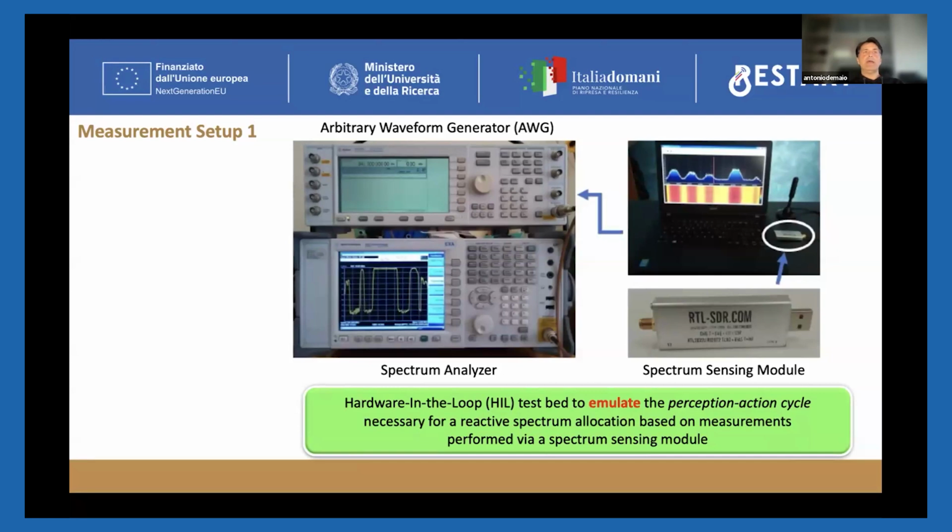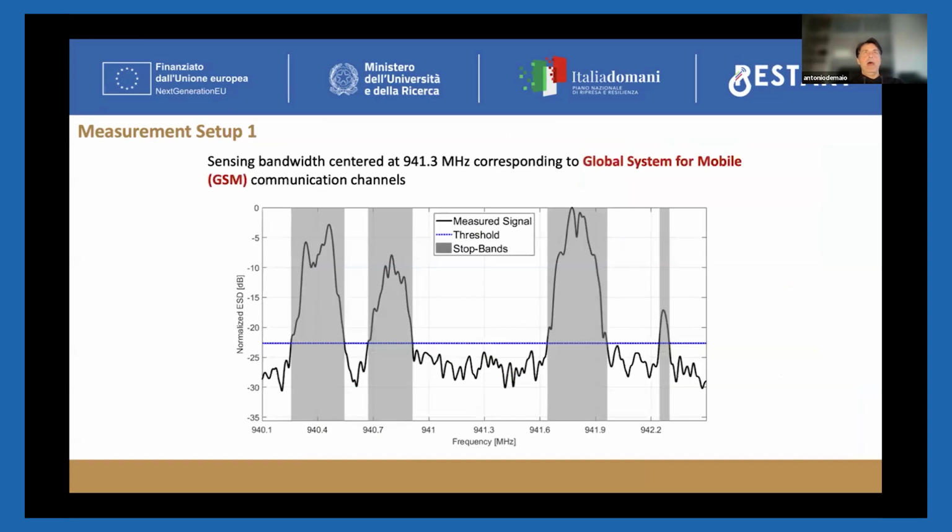And finally, a spectrum analyzer to measure the synthesized waveform spectrum and to demonstrate its compliance with the spectral constraints that have been forced at design stage, and also its fidelity with the nominal counterpart, I mean the waveform which is at the output of our MATLAB.